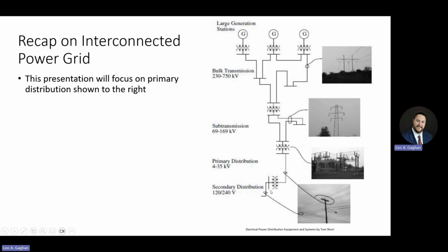That little transformer right there is representative of what you guys would probably be used to seeing as just a can at the top of the pole. And then this is actually bringing it to your house. Your house would use 120, 240, where it's a single winding that has 240 with a center tap that's grounded.